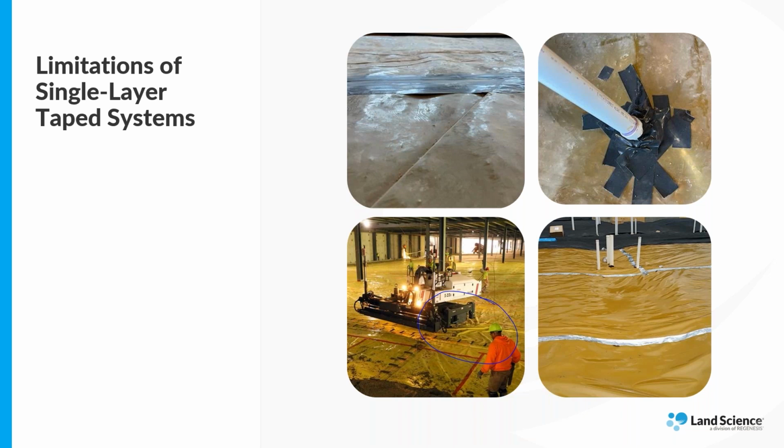Another consideration is activities after a barrier system is installed. Will equipment be driving onto the barrier after it's installed and inspected? The machine you see here is a laser screed, and every time it moves, it has the potential to open up a seam, or worse, tear the actual sheet membrane. We deal with laser screeds on our projects all the time, and we also have some specific requirements for how they're used once our barrier is installed.